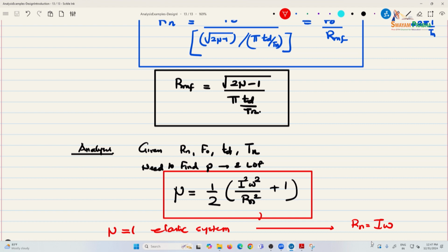What does I represent? What's the physical representation of the impulse? Yeah, time and pressure, the load, right? So if you have forces, k times x, and you're designing for kx, here it is I, and instead of displacement it is angular circular velocity. So they are analogous to each other. So this is a strong check for an elastic response, and we'll look at these and a few examples maybe tomorrow, I think it's past time.